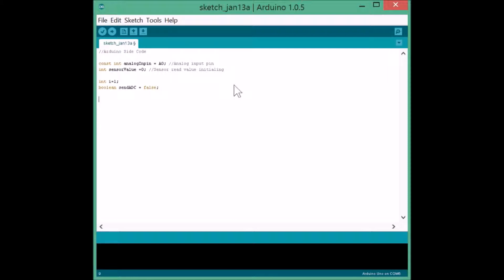The Bluetooth module I am using uses a serial port profile. So basically it would be having 5 pins. The first would be a key pin, the next would be the VCC, a ground, and the RX and TX.